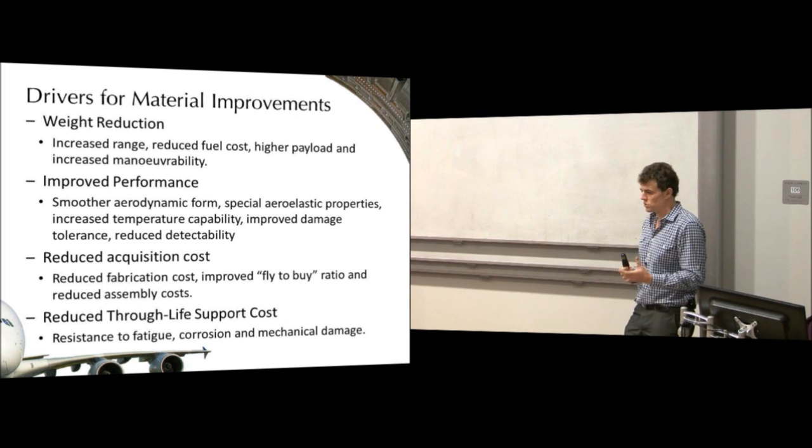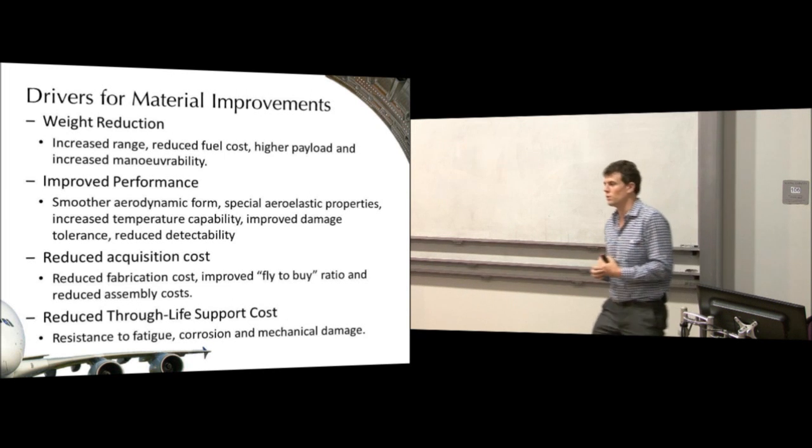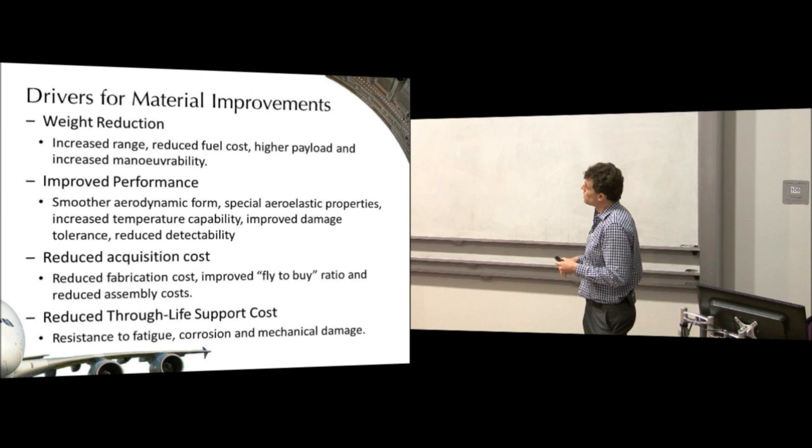But if you can reduce the huge drag overheads that come with those increased speeds by using special airfoils, then you can make a lot more money with your aircraft. In order to do that, it's very hard to make some of those airfoils out of aluminium because they're hard to form into the right shapes, whereas composite you can form into very precise shapes.